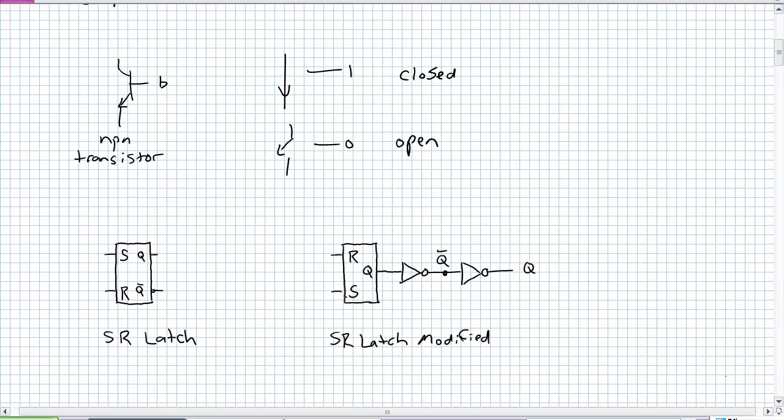Okay, the next device inside a 555 timer is an SR latch. I certainly hope you're familiar with this guy. Let's just do a super basic review about what an SR latch does. When it's active high, and I am neither setting nor resetting this device, what does Q do? Well, Q stays the same. Now I set this thing. What happens to Q? It sets to 1.